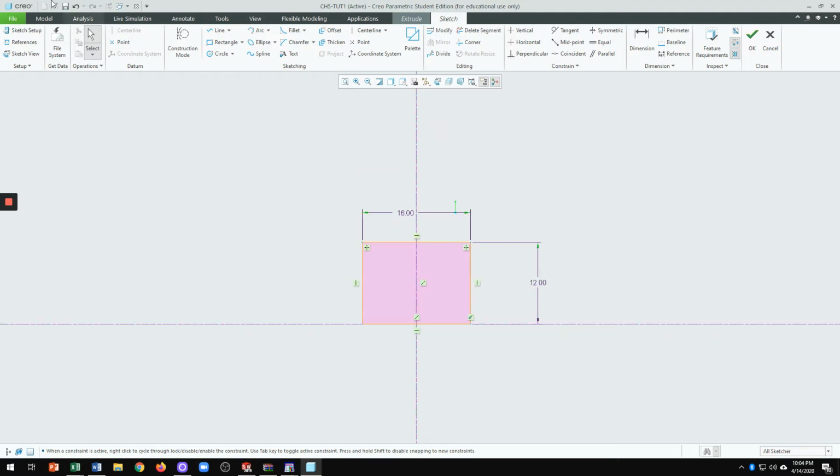So next, I'm going to create either a semicircle or just an arc or a circle. I'm going to just use arc, okay? So I'm going to start from here and then just move along here. Then you move it up until you see that? You want the center point. See that the center point is moving up, correct? To coincide with that horizontal line. So that means you have the tangent, you have symmetric, and that's what we want.